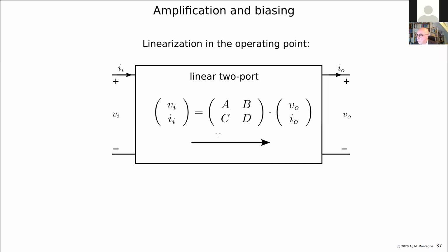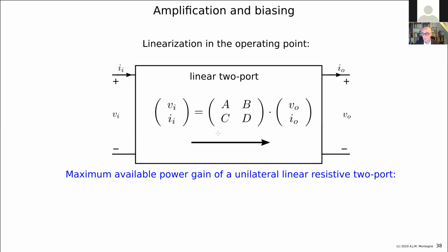But we don't worry about it anymore. We just replace it with controlled sources, as we have done in the bachelor course where we discussed these 2 ports. And that's why we usually speak of active devices, because we use models like this for them. But remember, the transistor itself is a passive device, but the whole constellation, the whole structure with the bias sources around it makes it an active one.